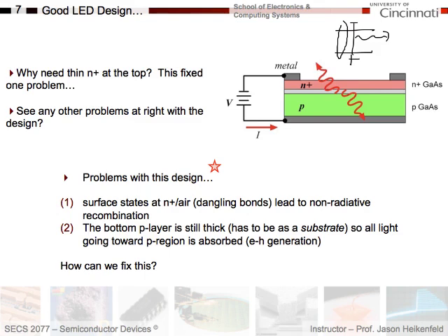So as it was expecting to keep having bonding with continuous semiconductor, you've cut it there, and you've got all these bonds that are unformed, which are defects, which can gobble up emission. And so what happens, if I make this layer too thin here, quantum mechanically, my emission energy can then couple to the surface and recombine non-radiatively. And this is a big effect if you have your emitting layer too close to the edge of a semiconductor device. So that's a problem.